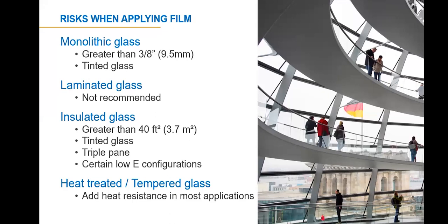Laminated glass: Madico only recommends one film applied to laminated glass, our Nova 70. We don't recommend using other films since the film can absorb too much energy, and this can lead to a crack or delamination of the laminated glass.